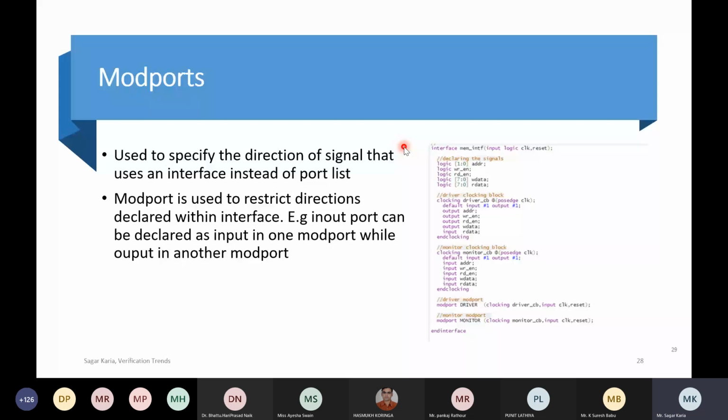How do you constrain that in SystemVerilog? Inside a class, you declare those variables as rand, any variable like A and B, and then you constrain them, giving the legal space. I guess in the last lecture, Usha ma'am was talking about giving legal values and constraining your stimulus. In SystemVerilog, there is a constraint keyword. You can give a constraint saying that my P1, which is 2-bit, can generate a value of 00, 01, 10 or 11, but you say please don't generate the value 00 because my design doesn't allow it.